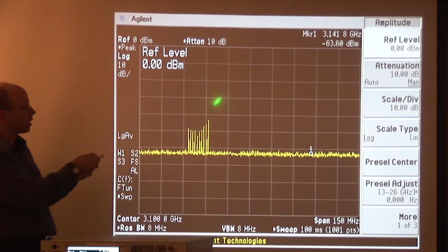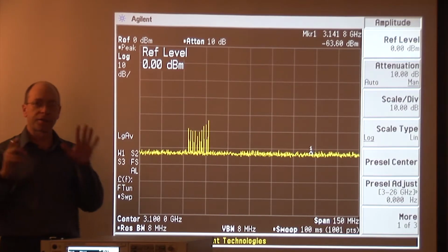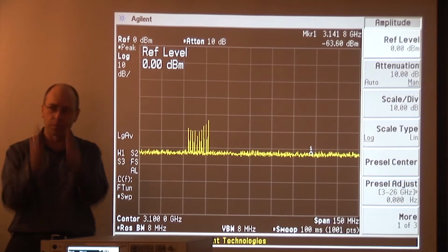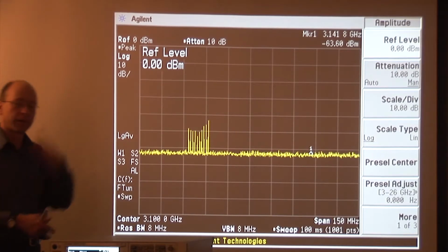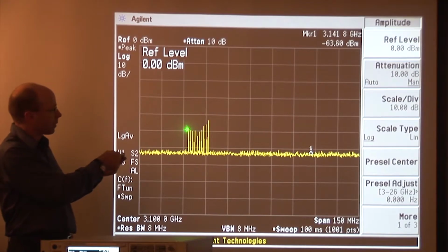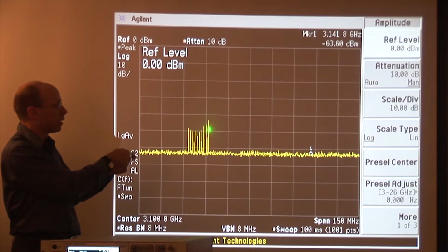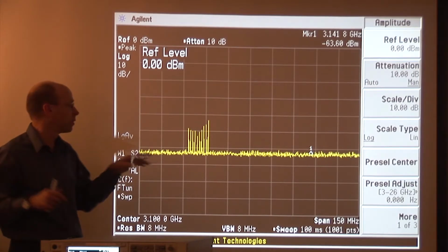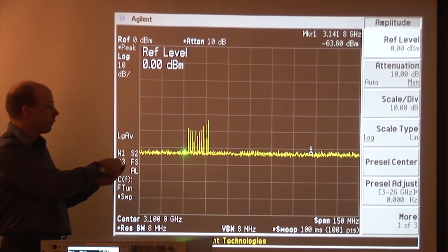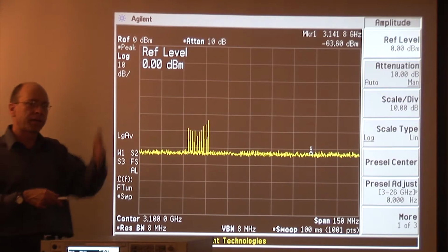And so what we see here is the radar's little antenna pattern, if you will, which the way Brent has programmed it has 10 pulses in the main beam and then simply switches itself off just to make it simple. We're not replicating a really tricky, complex antenna pattern. So what we're seeing here is the time domain behavior of the 10 pulses in the radar burst in its main beam, displayed on a frequency domain display which is intercepting them every millisecond as we sweep across the frequency.